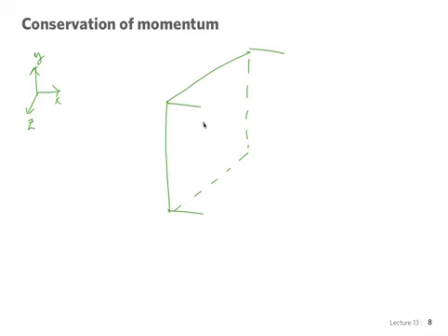And so now I have, as stress vectors, I'm going to point downwards in the negative y direction, and I'm going to point backwards there in the negative z direction, and that is sigma. So these are the ones that are going to be considered positive, because since the normal points in the negative direction, all the stresses that point in the negative direction, I'm going to keep a positive sign with it. Okay, I'm going to keep these. That's the sign convention that is used.